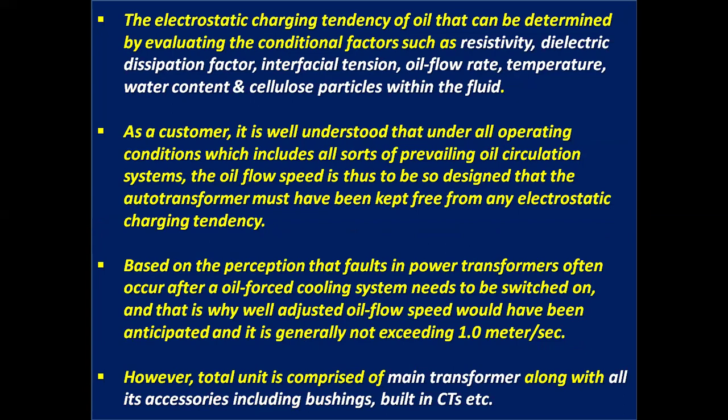The electrostatic charging tendency of oil can be determined by evaluating conditional factors such as resistivity, dielectric dissipation factor, interfacial tension, oil flow rate, temperature, water content, and cellulose particles within the fluid. All are vital factors.